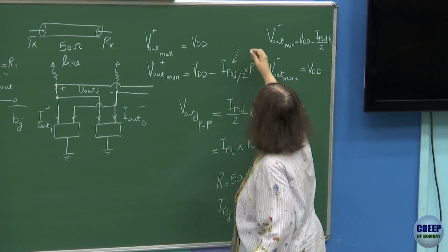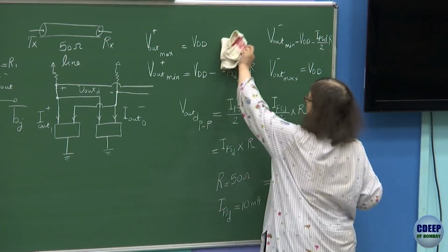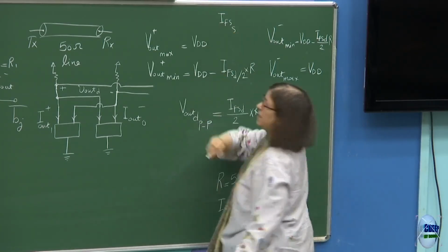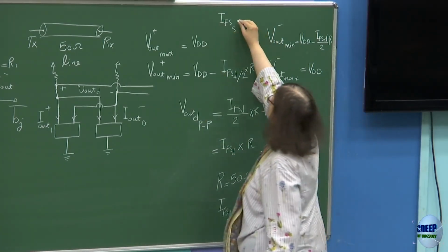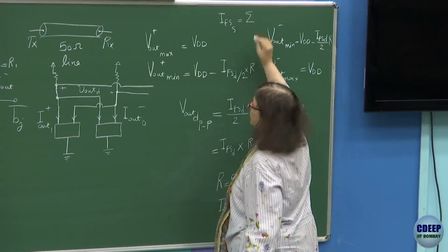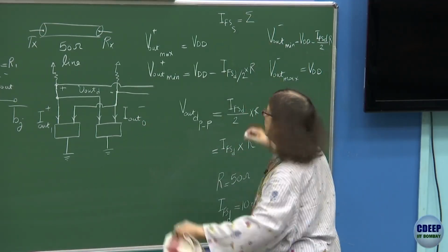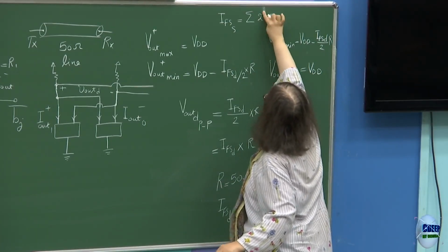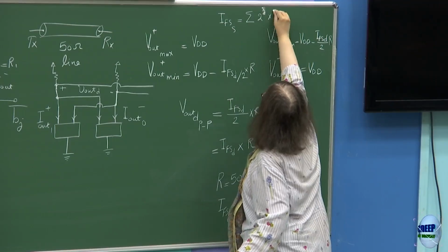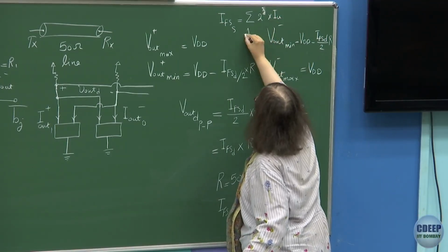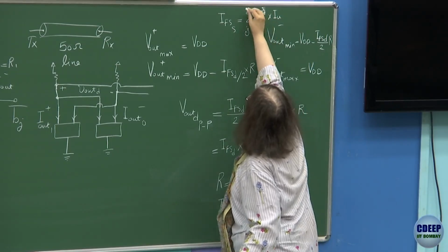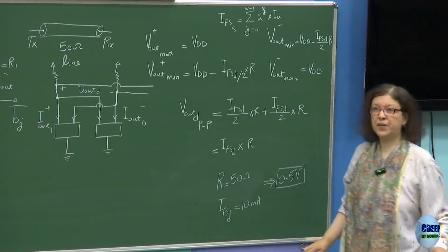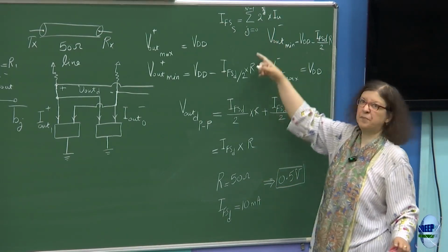See, this is actually this whole thing. I can write it on the top. I full scale, single-ended now, is actually the summation of all currents with a weight of 2 to the power J, multiplied by I unit, where J is changing from 0 to n minus 1. So this is the single-ended one.